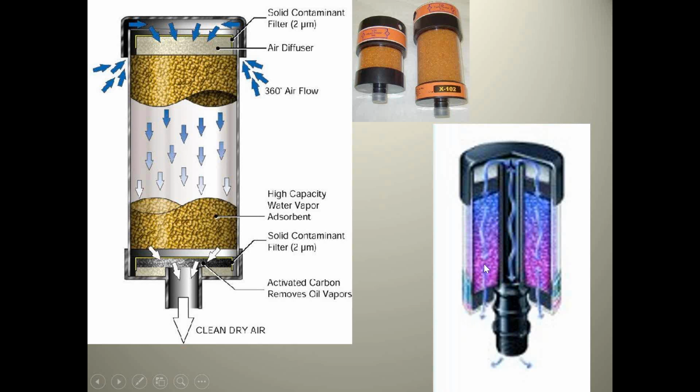The Desiccare model here, the moisture comes up through the desiccant on the side. So if these get saturated, at least the moisture drains to the side. And like I say, they're very expensive to change, but they need to be changed. They can be dried with an air dryer. If you need information on that, give me a call, or I won't talk about it on here because some of the breather manufacturers may get mad about that.